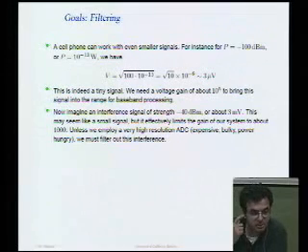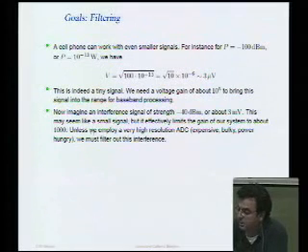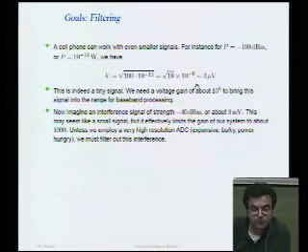It's 60 dB bigger than the signal that we're trying to observe, right? And that means that if we just simply were to apply gain to our system, that interferer would actually limit the gain of the system to about 1,000. In order to take 3 microvolts, let's say, up to 300 millivolts, in order to, let's say, digitize it, we need a gain of 10 to the 5.